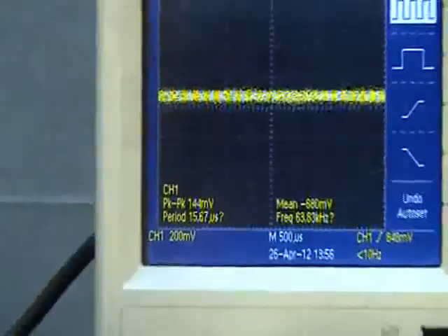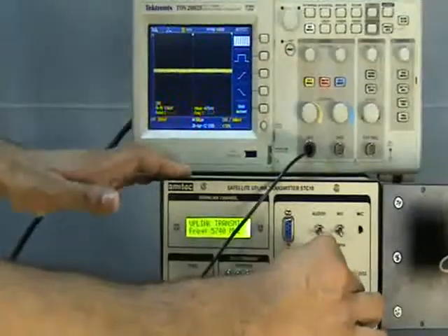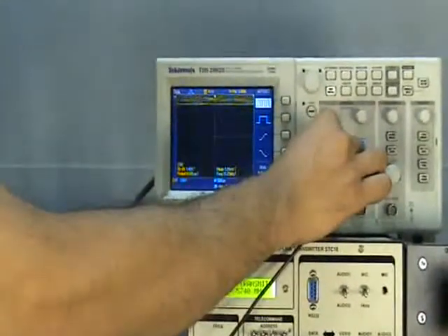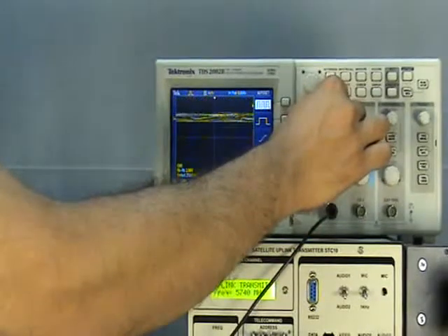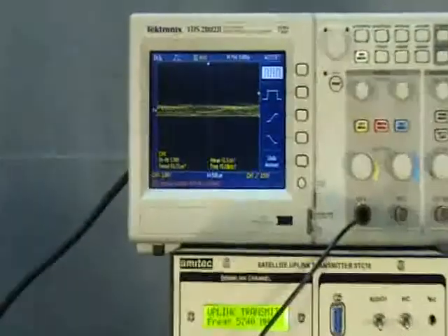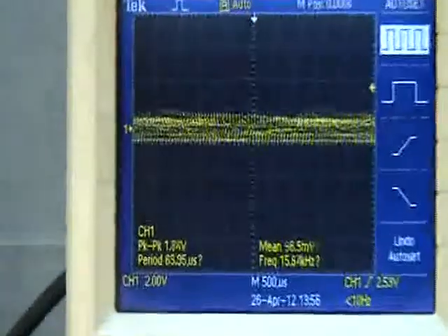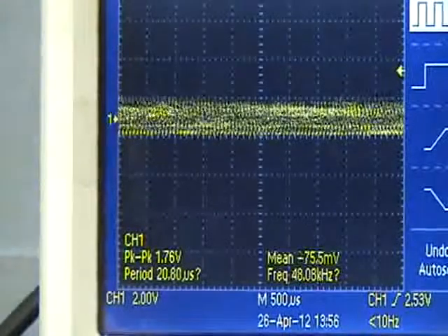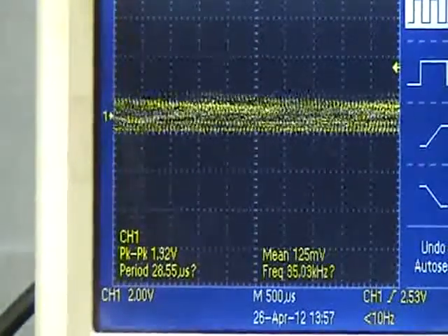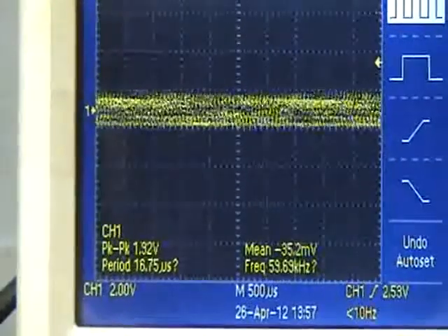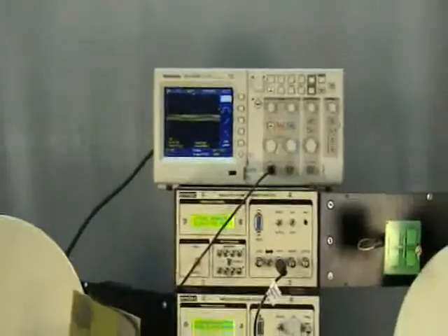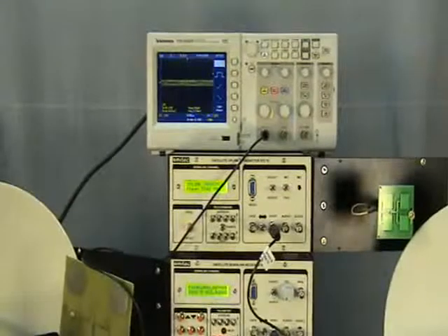And now we try to feed some signal at the transmitter baseband input. We can keep it AC coupled also. Now as you can see, this peak to peak is reading around 2 volts or 2000 millivolts. So 2000 millivolts is the peak to peak signal which has 150 millivolts of noise already embedded in it. So the actual signal level is 2000 minus 150, that is 1850 millivolts.